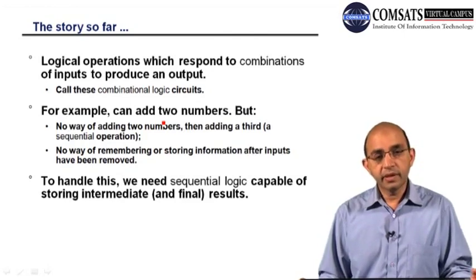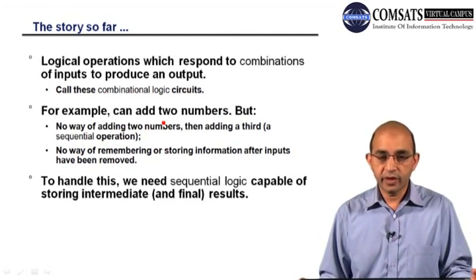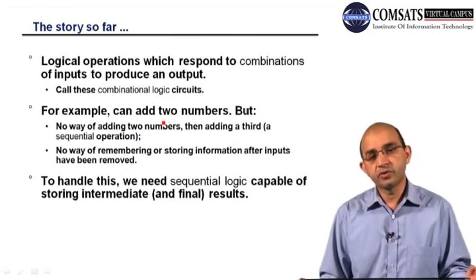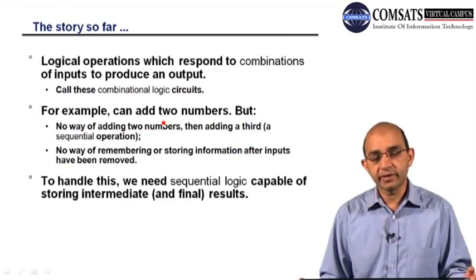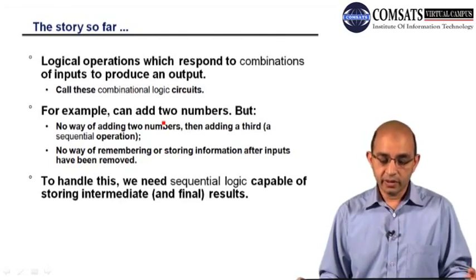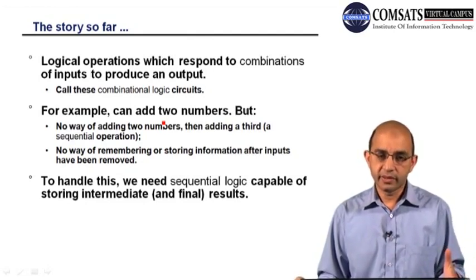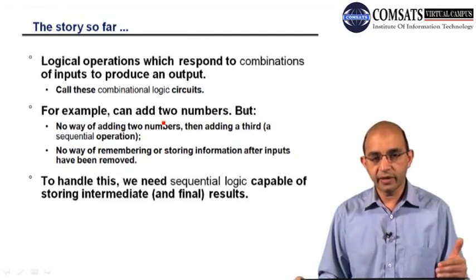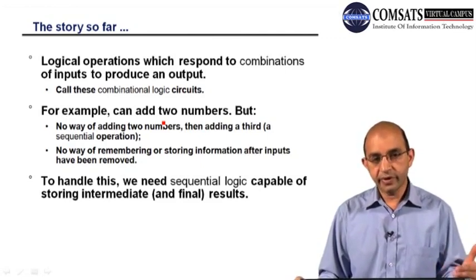But in another case, let's assume that we have to add 2 binary numbers. As we know, if we are using adders, we will be getting a sum and a carry, and the carry has to propagate. So we have to store the carry somewhere else. This is one example where you can think about the requirement of sequential logic. You can add the corresponding bits, store the sum and the carry somewhere, and then move to the next bit. So this is one requirement.